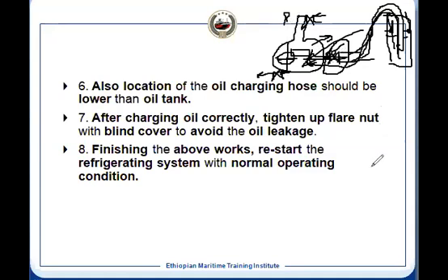Now there will be some air in the crankcase which you cannot remove. How will you remove it? You can remove it. It means when you have done the pumping down, and after that, once you do the pumping down, for this operation, cleaning the crankcase and removing the oil, you'll have to do the pumping down. And then after that, what you do, you can purge it on the condenser. This air can be purged.